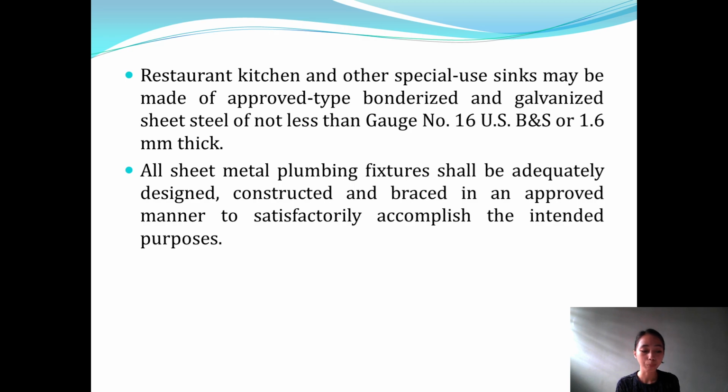The most common and most economical material for domestic fixtures, such as toilet bowls, urinals, and wash basins, is vitreous china. For more durable day-to-day use in kitchen sinks and laundry tubs, stainless steel is recommended, but enameled pressed steel and suitable plastic materials may be acceptable. Plastics are commonly used for bathtubs, shower trays, laundry tubs, cisterns, wash basins, and toilets, and are often reinforced with fiberglass for extra strength and durability.